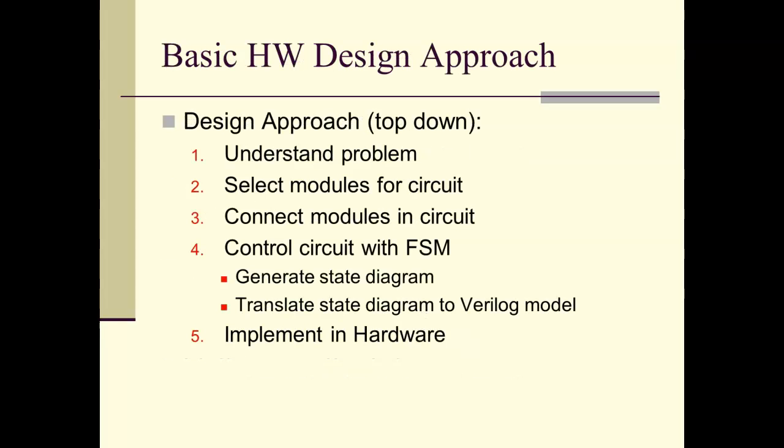So the basic approach to hardware design is we're kind of taking a top-down approach. Number 1, understand the entire problem. And once you understand that problem, you can start selecting digital modules for that circuit. Now, my contention is there's just not that many digital modules out there, and those modules don't do much, but you can do anything by making circuits out of those modules. So use those modules. Don't try to make a magic circuit by changing Verilog into a programming language, because it's not.